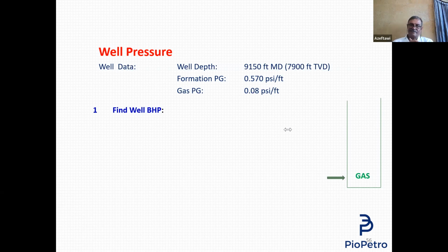The answer is, these 4 compressors are working now. You open the 4 valves, so air will be fed into this manifold. The compressor that feeds this manifold with 400 psi, none of the other compressors will work, because the one with 400 will feed this manifold with 400 psi. So this manifold is 400 psi. You have a compressor at 300 psi. How will it go in? 300 cannot access the 400. The other 3 compressors will not work.